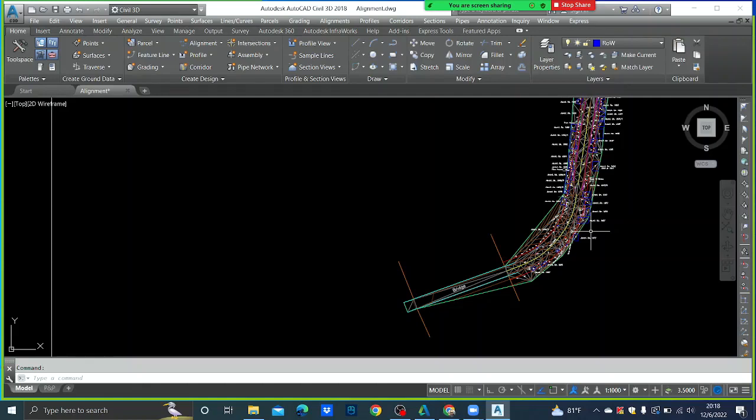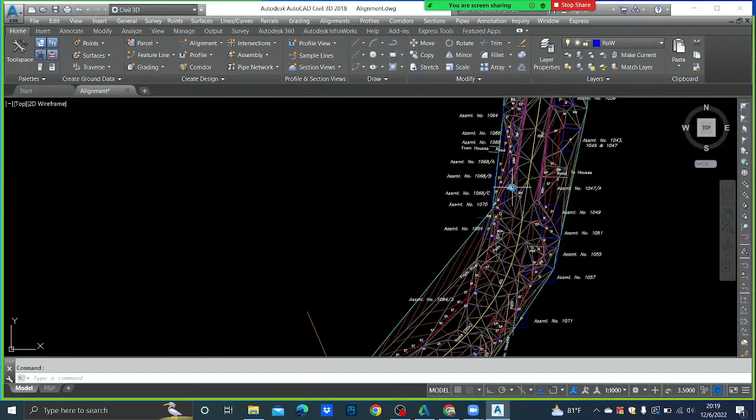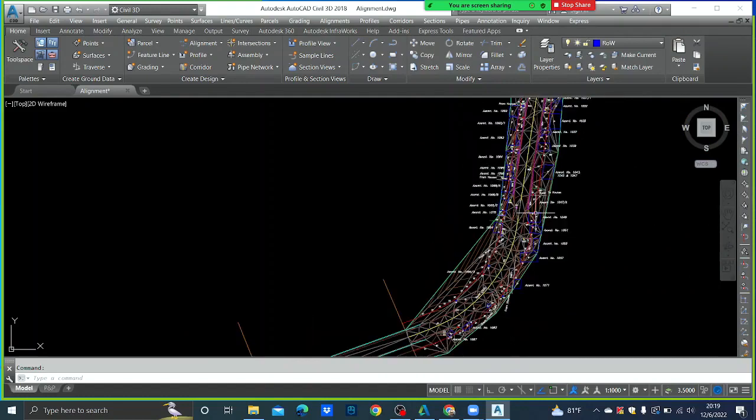If you are going to decide whether your alignment should go to the mountain side or the precipice side, 5 millimeter or 10 millimeter accuracy is okay. But when it comes to the payment for contractors, of course we are going for 5 millimeter accuracy, right? That is true. But to decide, just think, this side is precipice, this side is mountain. Just think it is a mountainous area.